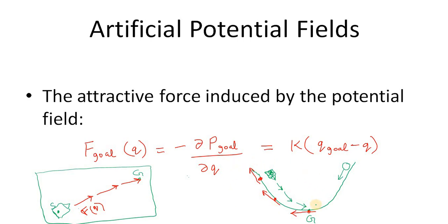So this is totally mathematical. This field in actuality doesn't exist. We create this artificial potential field purely from a mathematical function, using a quadratic function. And the advantage of this is that when we apply this in the robot, in the real environment, the robot acts like it is experiencing some kind of force that is attracting this robot towards a goal. Okay.